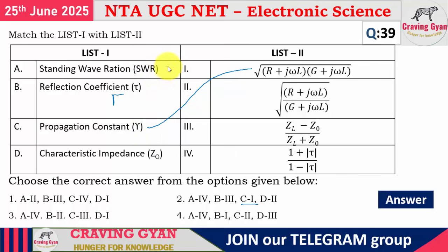The standing wave ratio rho you are going to get equals (1 plus mod gamma) divided by (1 minus mod gamma). Say suppose mod gamma equals 0, then rho will vary from 1 to, say suppose gamma equals 1. Here they have given tau equals 1. Then the standing wave ratio will vary from 1 to infinity. Important. Then the reflection coefficient gamma is going to vary from -1 to +1.